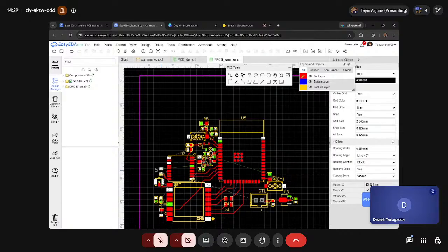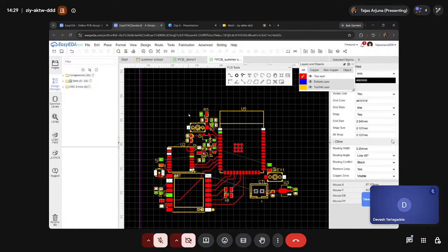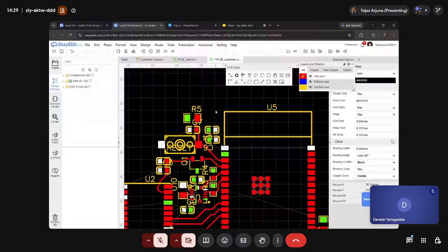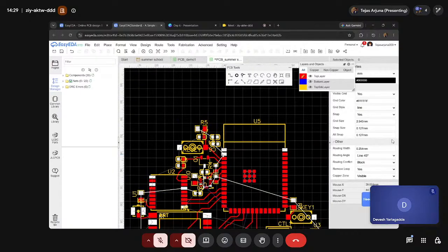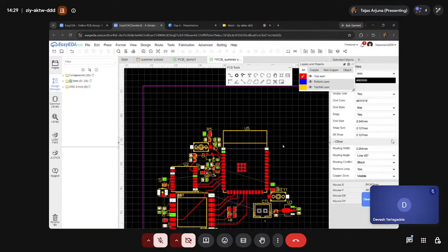Why we are avoiding that type of configuration is because when we keep the VDD plane in the top layer, the decoupling capacitor is completely ignored. The plane will cover the VDD part directly. It will also cover this, but there will be no point if it is directly connecting to the VDD part. And that is one reason.